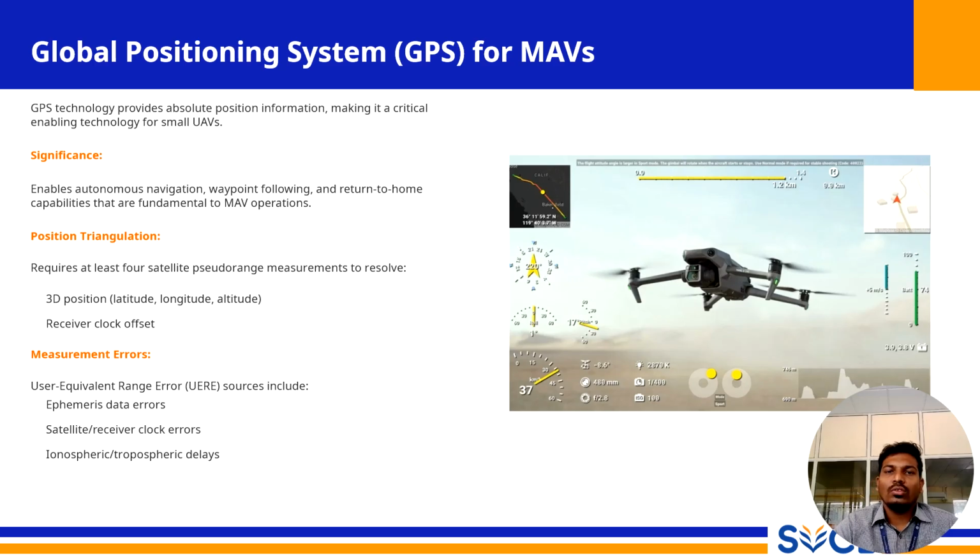The fourth measurement is needed to resolve a critical variable, the receiver's clock offset. The timing requirements for GPS are so extreme that a small inaccuracy in the receiver's inexpensive quartz clock would lead to enormous position error. The fourth satellite signal allows the receiver to constantly correct its own clock against the highly accurate atomic clock in the satellite, thus ensuring a precise positional lock.